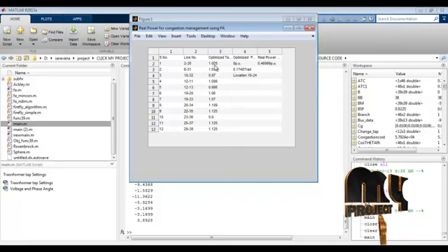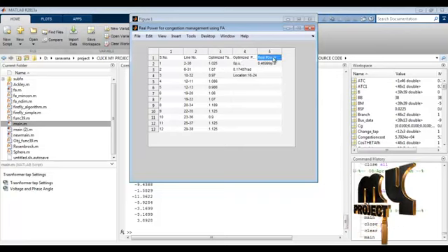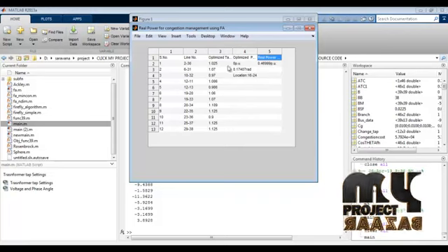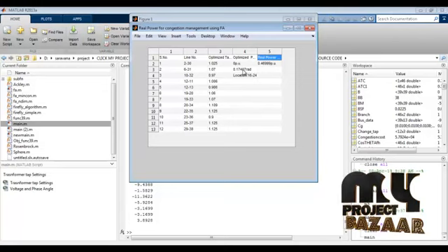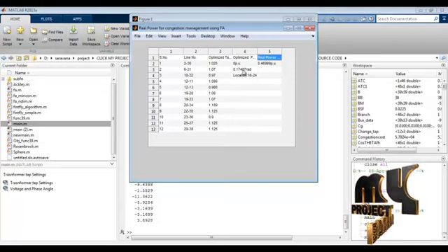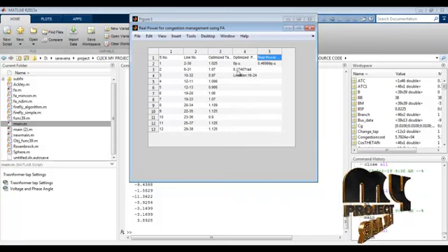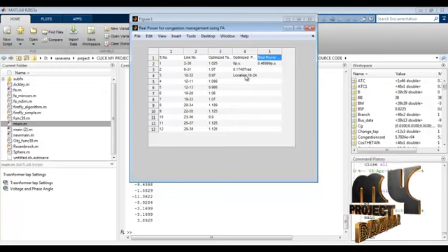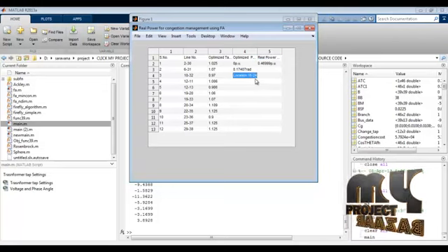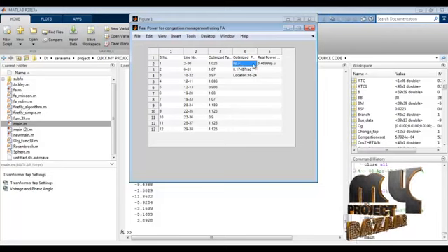We optimize the data for that, with per unit optimization and the real power injections of this data. We see how the different parameters are located to get better results across the different lines. So this is real power congestion management using the firefly algorithm. We located the best location for placement in the congestion management system: line number 16 to 24 is the best location, with an angle and an optimal value in per units.